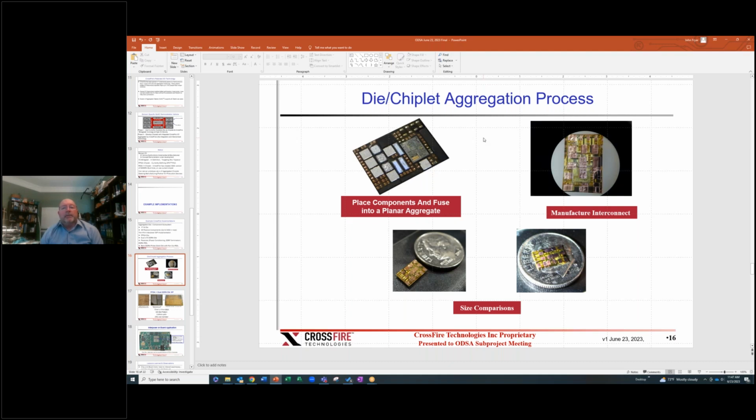And they're probably 20 micron pitch, 10 micron traces, something like that. I don't take those as hard, but that's the ballpark of where they're at. Yeah, okay. I think even with the public numbers that they have there, they're more towards 2 microns and below. But the idea is certainly correct.